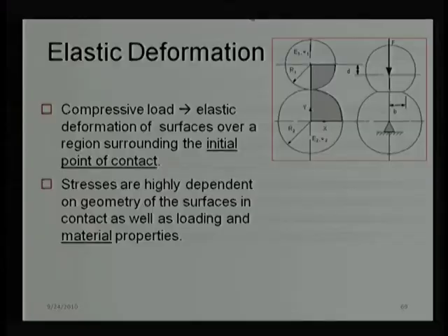This was related to viscosity variation, with the temperature and with the pressure. But when we were discussing viscosity variation with the pressure, we said that we are not accounting for the change in surface geometry, the change in film thickness, and obviously the deflection of the surfaces. Without that, it is only a half treatment given to elastohydrodynamic lubrication.